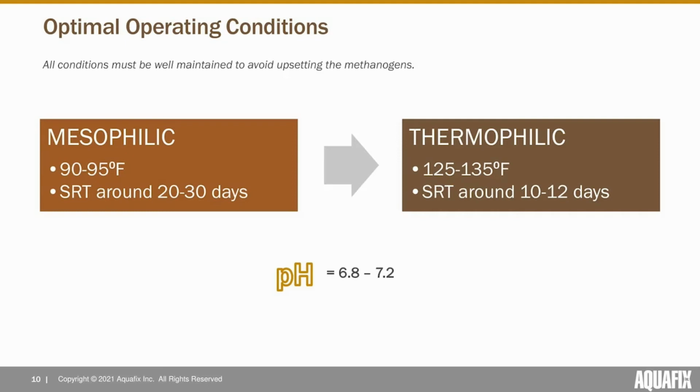These temperatures and ranges are significant because, one, methanogens are fairly slow growers. You need to have time for them to grow fully in the sludge in order to degrade your substrate. And two, the further you go outside of this range, the less methanogens are able to degrade the substrate, because methanogens are a fairly narrow range of organisms, and the further you get from these optimal temperature and pH conditions, the less of them will be doing anything. So you might end up at pH 6.5 with only a couple methanogens producing methane at that point, and the rest will just be sitting there, being a bit lazy, not doing anything useful.